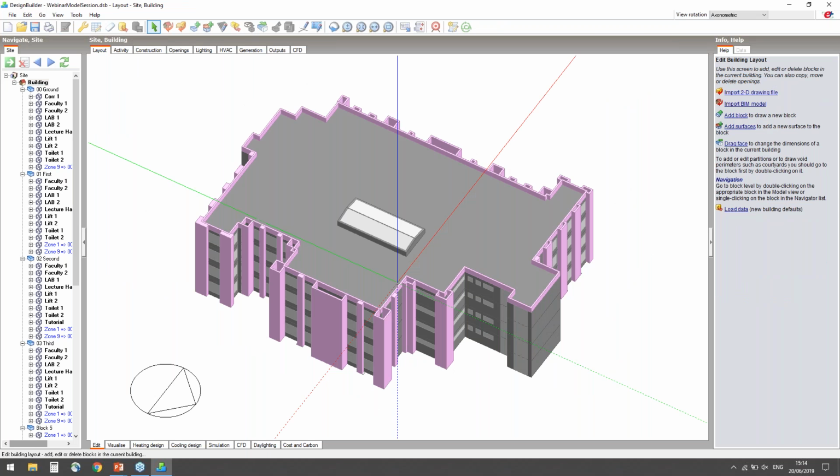In this project, the layout and activities are fixed according to the design specification, but there is scope to improve constructions, shading, lighting, and HVAC. So as we saw, these are all our design variables in this exercise. I am not going to review the model data tabs, but instead will show you in the optimization setup dialog some of the key data such as constructions that were used as design variables.